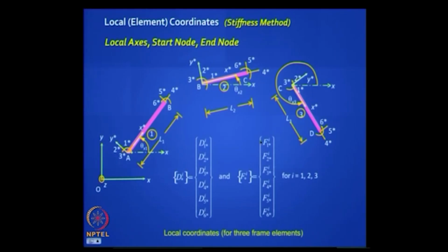So I have a displacement vector 6 by 1, and a corresponding conjugate force vector. Does this make sense? Now I have created a framework with which to start playing my game, but without a framework which all of us share, understand and agree to, we will have problems. Is the notation clear? By the way, different books give different notations; you shouldn't get confused, the concepts are the same. You have to define the local axis, the start node and the end node, and everything falls into place. The theta is crucial here.